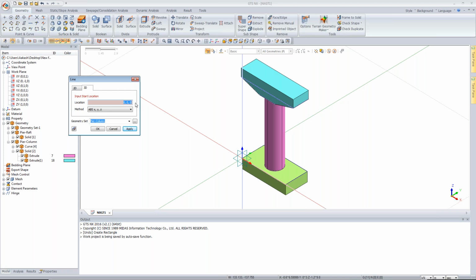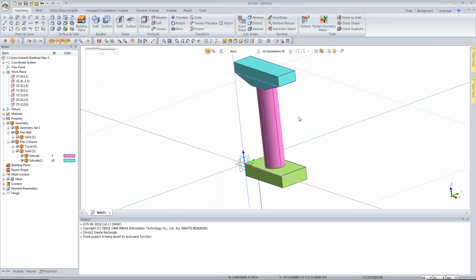First coordinates, let's suppose it is at 1, 0.75. You can first calculate it and draw a rough sketch so that you get a rough idea of where exactly you want to place it. Then 0, not 0, I will just start at the bottom of the raft. So minus 1.2 and 0, 0. Let's say it's an 8-meter long pile. Fine. So this is your first pile.